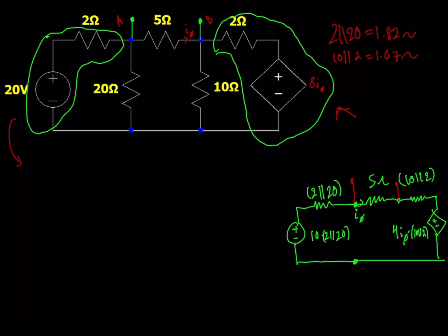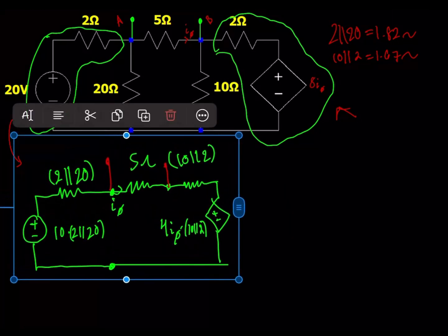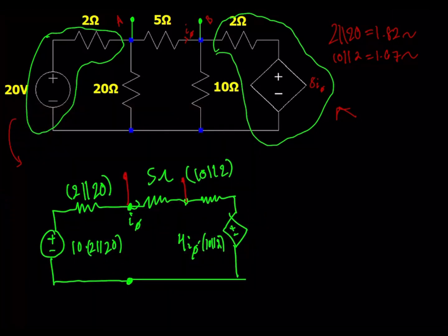So I'm actually going to move the circuit over here, blow it up a bit. So again, it's one loop, everything's in series. Just write your simple KVL and set those voltage drops equal to 0. Well, I'm not going to show the computation here, but you'll get that I0 is equal to 1.2 amps.